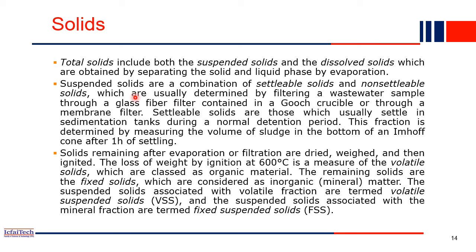So the next important parameter is the solids. We have seen how we removed the solids from the water during the water supply treatment. Here also we'll be seeing how much solid is present in the wastewater. So we call it total solids, which includes both suspended solids as well as the dissolved solids present in the water. The suspended solids we can remove through filtration, what we have done earlier in the water supply. Also we will use sedimentation tanks, and the settleable particles will simply settle down at the bottom. Or maybe we can add some coagulants also, and we can remove the suspended solids from the water.